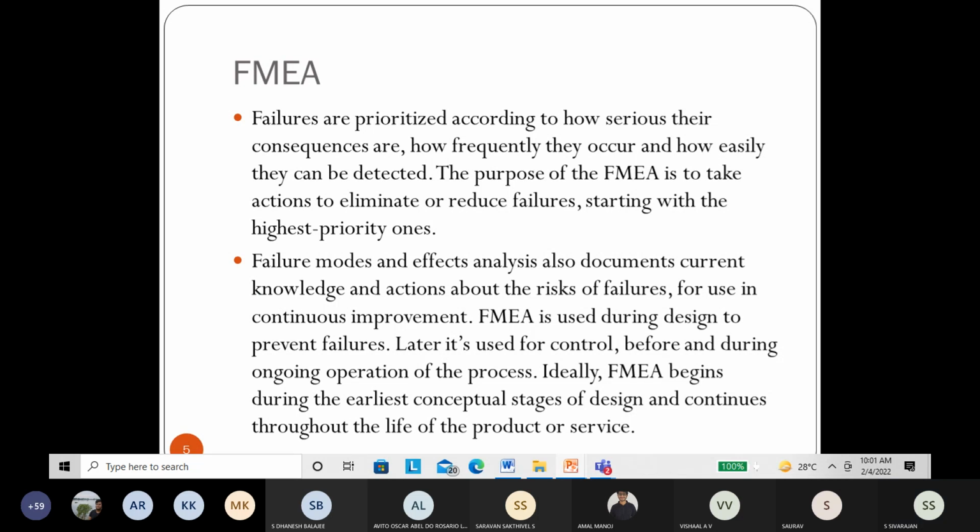So I will give one example. Because you are mechanical engineers, say you want to make a 1 inch hole, a 25.4 mm hole. I'm just giving an example. Ideally, you make a hole of 25.4 mm. And you know very well, from the machining process you studied, the drilling machine vibrates and the drill bit always makes an oversized hole. You will not get exactly the size we designed, because of component clamping and all these things.